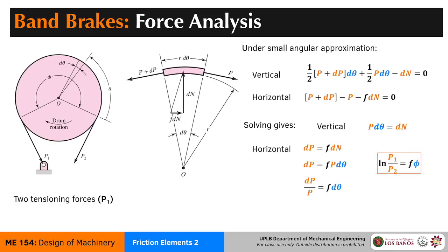And of course, if you want to get the torque that the band is exerting on the disc, we simply take the difference between the two loads. We are assuming here that P1 is the larger load. So P1 minus P2 times the radius of the disc itself, or the drum, or whichever you are causing to slow down or causing to have its speed controlled. So yeah, we just derived an old equation from NSI 11.